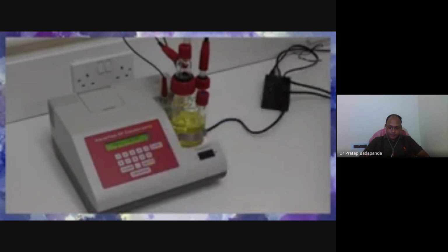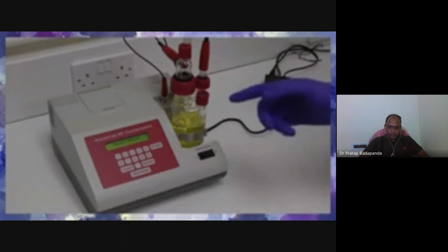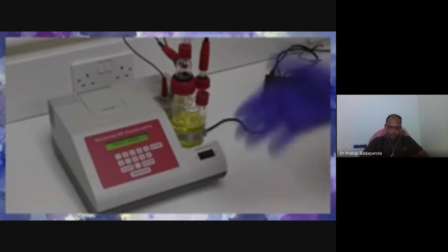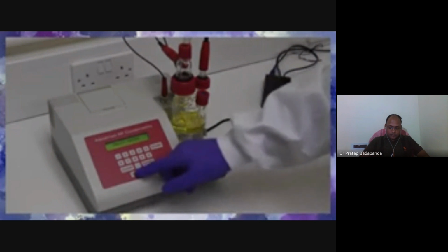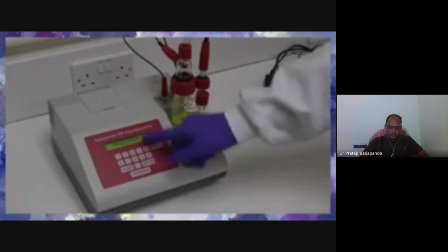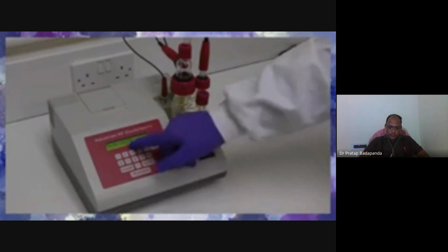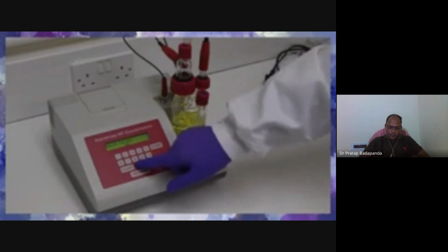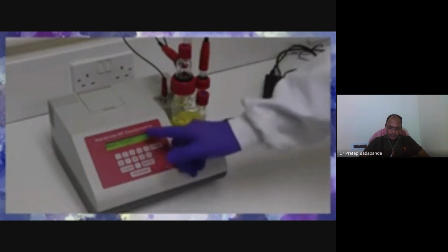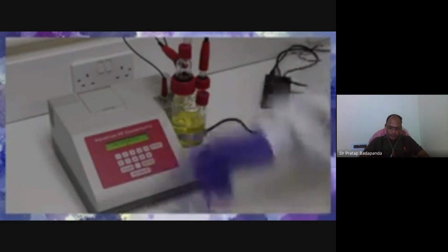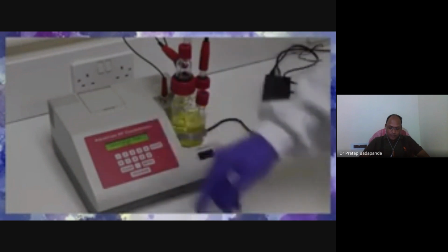The second parameter is Recall method. Methods can be stored in memory to avoid reprogramming from scratch. The next parameter is Result format. Pressing the decimal point will cycle the format through microgram, ppm, milligrams per kilogram, and percentage. Press Enter to select the required format and then Enter again to move to the next parameter.